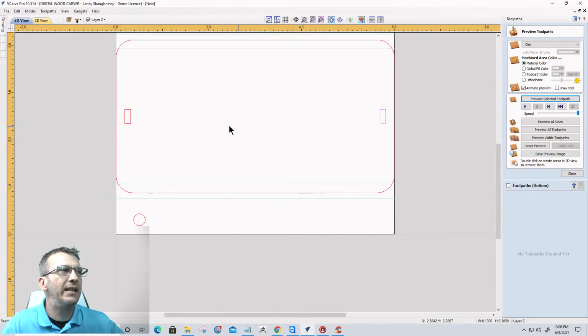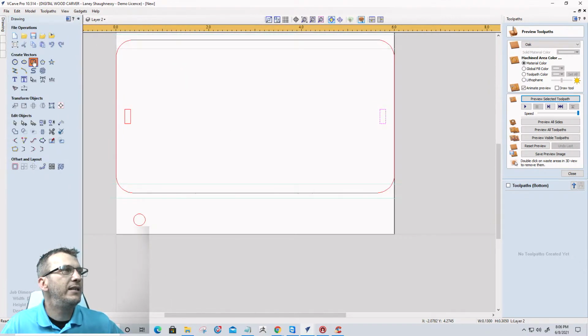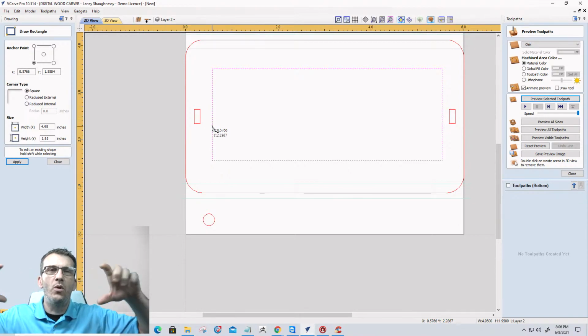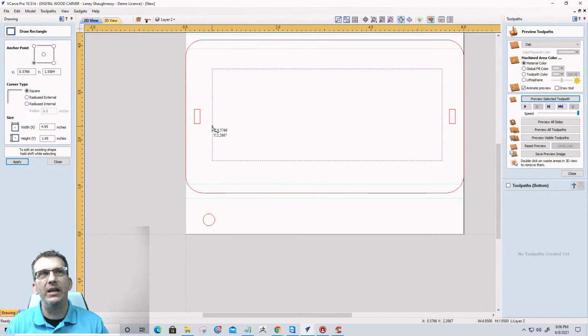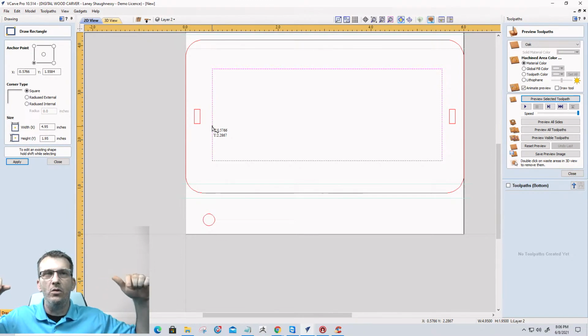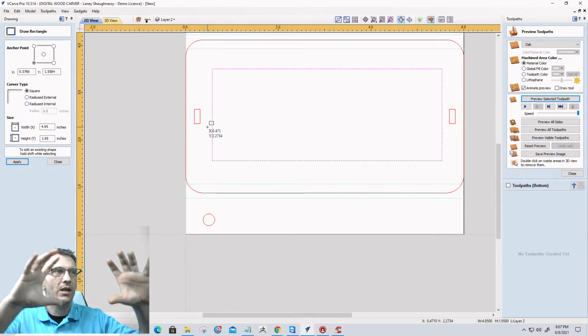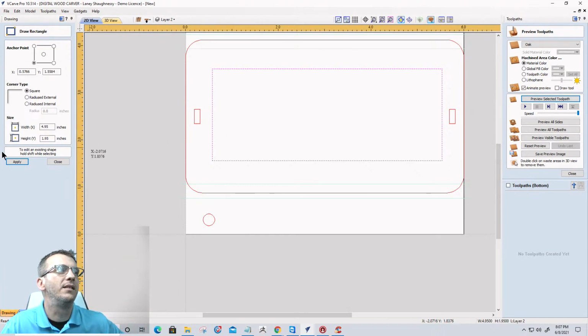If I'm gonna do any inlay work, any V-carve work, any laser work, I want it within this perimeter between these two magnet holes. I do not want to extend out to the edges. I want to make sure that I don't go over those magnet holes because I don't want to cut into them from this top side. So that's the only reason they're here on side 2, or the top side of this: just to give me a visual of where my working area is.